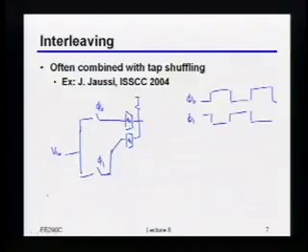Or in other words, the sample that was on phi 1 is what happened one bit before me. So that's how I'm going to build something that has a z minus 1 in it, right? Okay, so similarly, you end up doing exactly the same thing on the other clock phase, just that the meaning of everything is reversed.